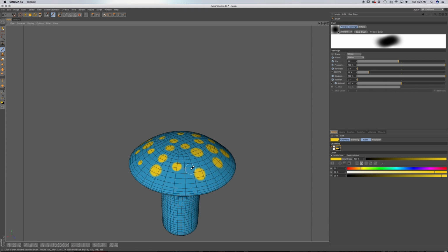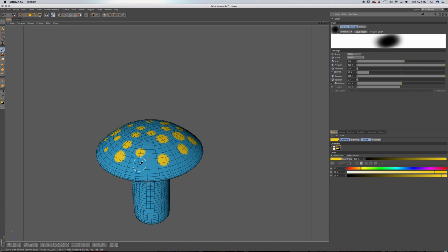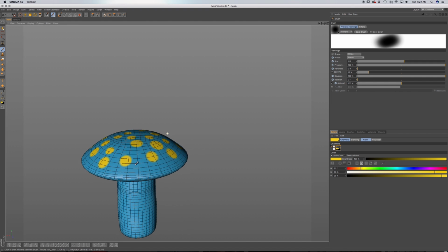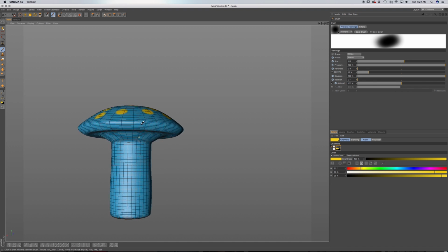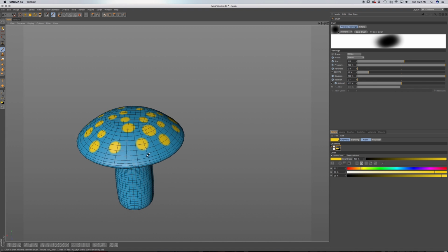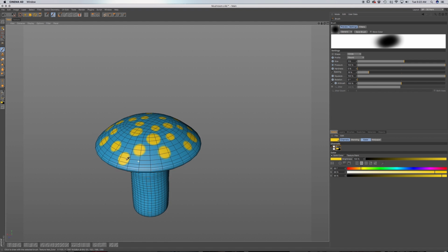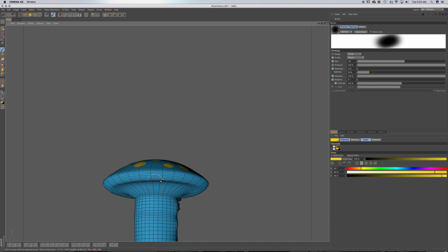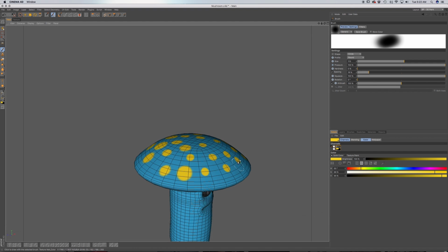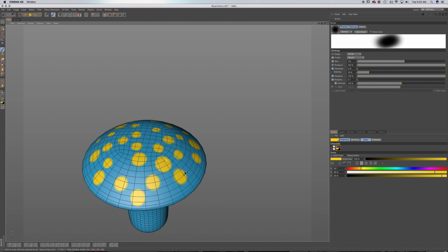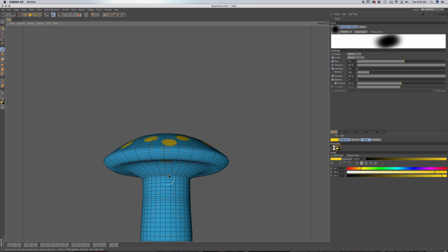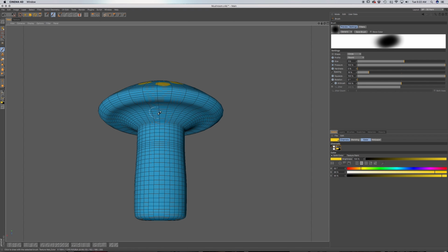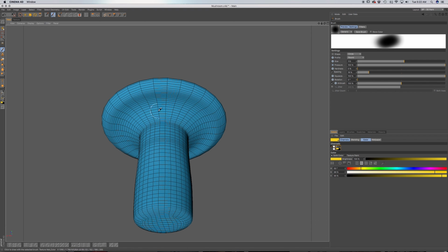And a seam is where a UV map comes together, where it's kind of split. It's not all one map. You're going to have different parts to it. So for example, there might be a seam that goes running right from the top. And the reason why you want to make sure that you have seams that aren't too visible is that you want to have them in the back, like around the back here, places where you're not really going to see them that well.